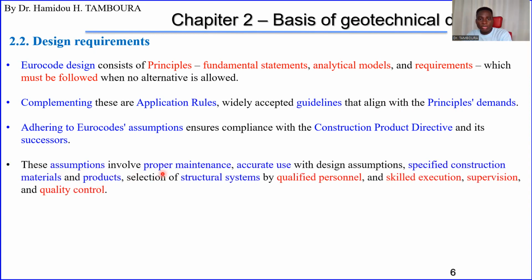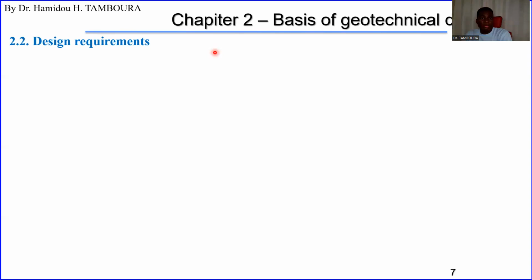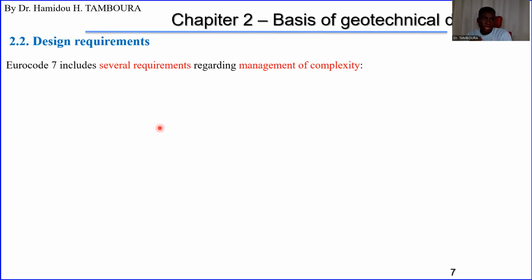These assumptions involve proper maintenance, use in accordance with design assumptions, specified construction materials and products, selection of the structural system by a qualified person, not anyone can select it, and skilled execution, supervision, and quality control. If you have this in mind, it will be easy to work.